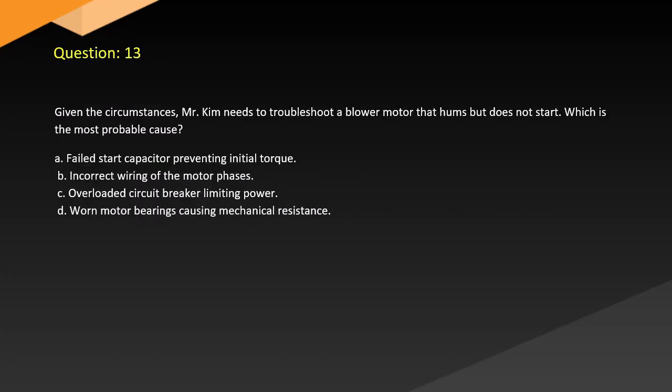Question 13. Given the circumstances, Mr. Kim needs to troubleshoot a blower motor that hums but does not start. Which is the most probable cause? A. Failed start capacitor preventing initial torque. B. Incorrect wiring of the motor phases. C. Overloaded circuit breaker limiting power. D. Worn motor bearings causing mechanical resistance.